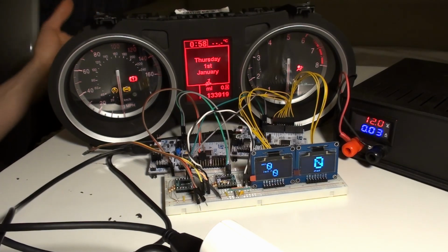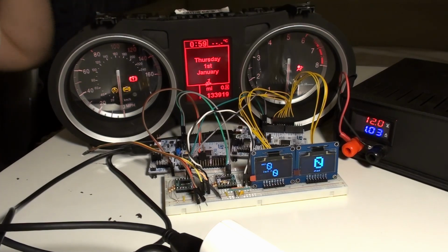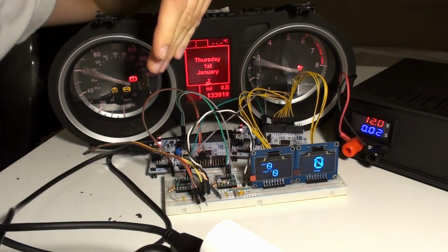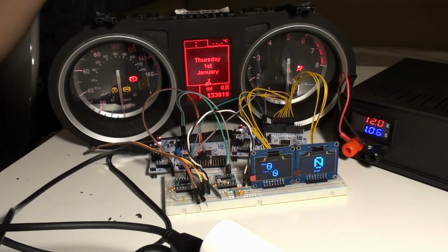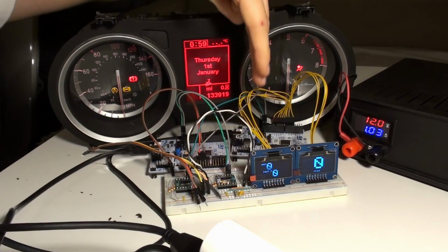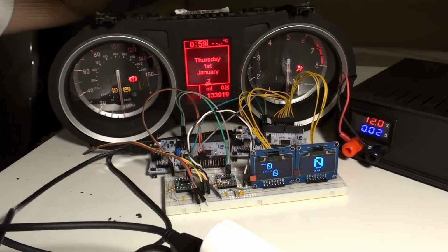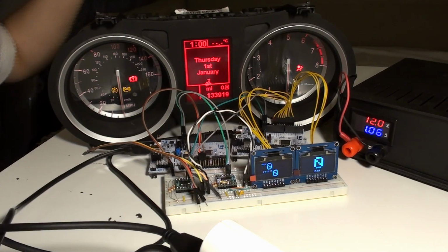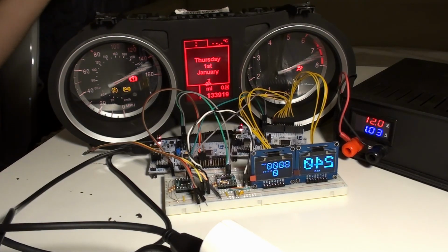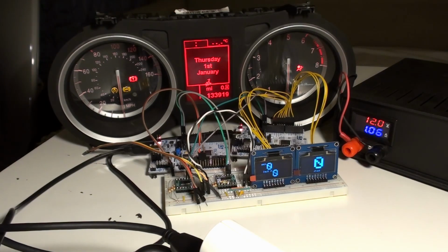Then I obviously have to do the electrical schematic and then the PCB layout, because now it's a dev board setup, all with those cables and so on. I'm going to copy the layout of this Nucleo that is available online and design a new layout to include the transceiver, passive components, and the programming header. And that's how I'm going to finish this. And then of course I'll need to order the PCBs, most probably from JLCPCB or somewhere. And then, to make it look at least somewhat professional, I'll need to enclose it in some kind of case that I'm going to design in 3D and then print it.